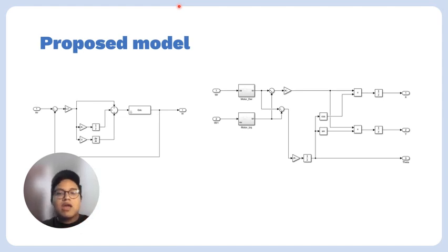Then we have our kinematic equations for x, y, and our direction. These equations are very important as they link the wheel speeds to the robot's spatial coordinates. The cos of theta and the sine of theta terms in the equations for x and y ensure that the robot's movement aligns with its orientation, which is a critical aspect for accurate path following. The use of R and L, the wheel radius and the distance between wheels, directly in these equations indicates an approach that tightly couples the robot's physical dimensions with its movements, enabling precise calculation of its trajectory.